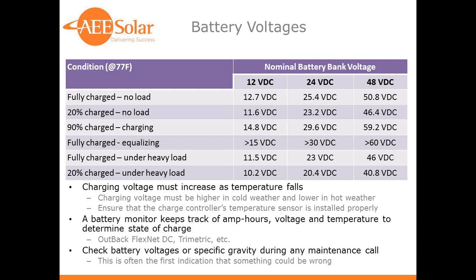It's kind of like having the fuel gauge in your car. It's not essential to the operation of the car, but if you don't have one, you're going to find yourself stuck on the side of the road from time to time. So it's the same way with an off-grid system. So battery monitors should be included in any kind of system that's off-grid and relying on the batteries.